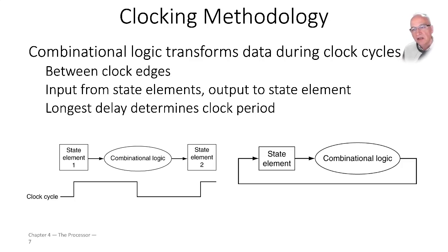So now we can think about what is limiting the clock period. Why can't we make the frequency higher and the clock period smaller? What limits the minimum amount of time that I have for a clock period is the delay through this combinatorial logic. I cannot have a clock period that will be shorter than the longest delay in all my combinatorial logic.